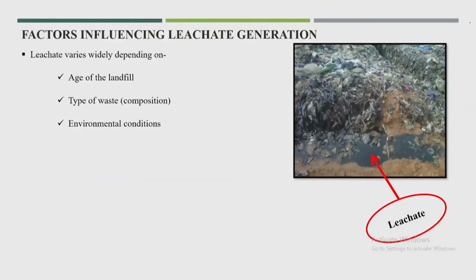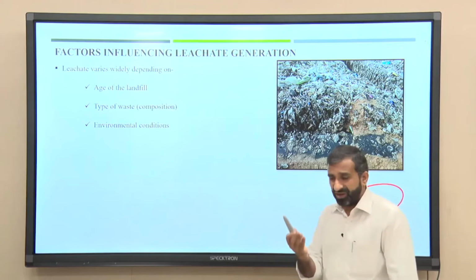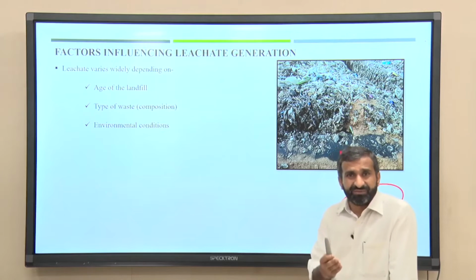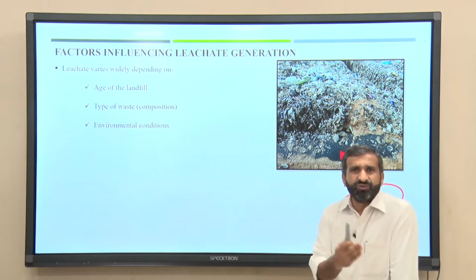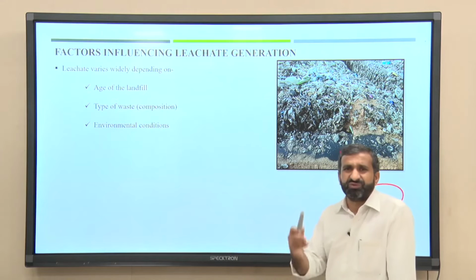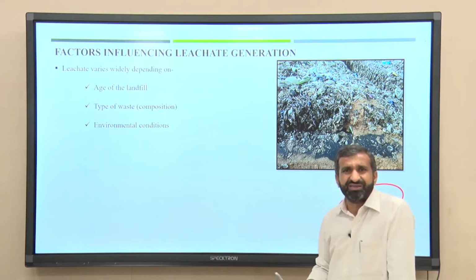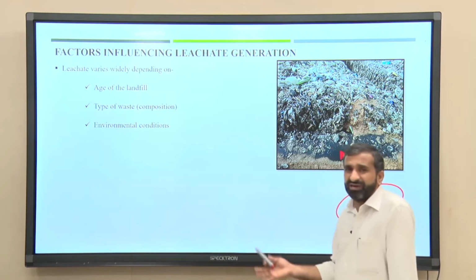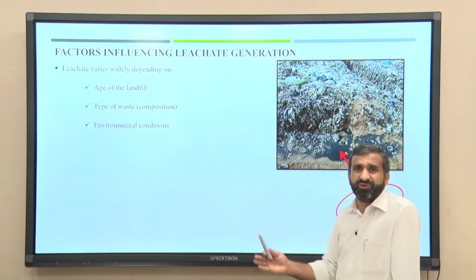And again, it depends on the type of waste. This was already discussed in the previous lecture. If you have non-biodegradable matter, non-recyclable matter and only inert material, or some reject from the treatment process, reaching the disposal site, then obviously you need not worry about leachate production. The leachate will get produced, but it will not be that polluted.